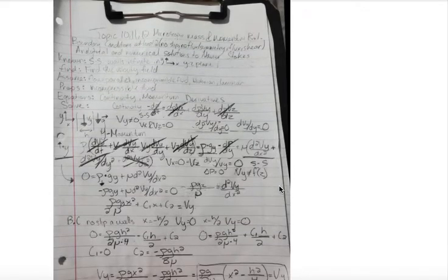So in this picture, you see we have two wide plates in the y direction, and velocity is going downwards in y. So we know that the velocity in the y direction is not equal to 0, but the velocity in the x and z directions is equal to 0. So when we use the continuity equation in the correct coordinates, which is rectangular, we get the change in density over time equals the change in velocity in the x direction over dx, plus the change in velocity in the y direction over dy, plus the change in velocity in the z direction over dz. dvx/dx and dvz/dz go to 0 because there is no velocity in there. So now we know that dvy/dy equals 0 based off the continuity.